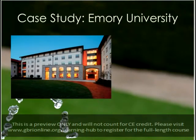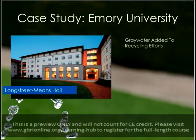From the rainwater harvesting system at Few and Evans, the architects moved on to combine this technology with recycled gray water at the 5-story Longstreet Means Hall. This is the first hall on Emory's campus to harvest gray water for toilet flushing. The gray water reclamation is projected to save more than 1 million gallons of potable water per year. The project system recycles wastewater from all sinks, showers, bathtubs, and laundry facilities for use in flushing toilets.